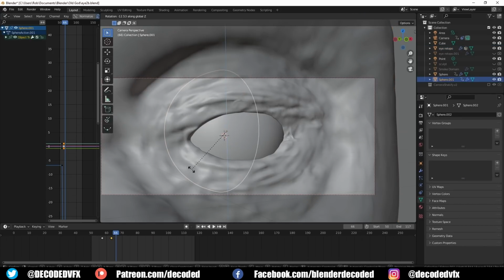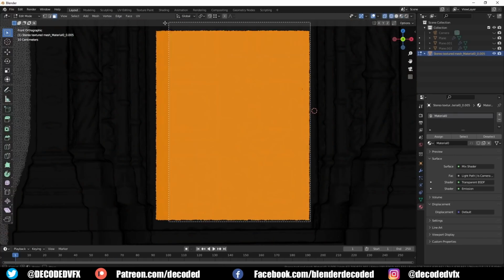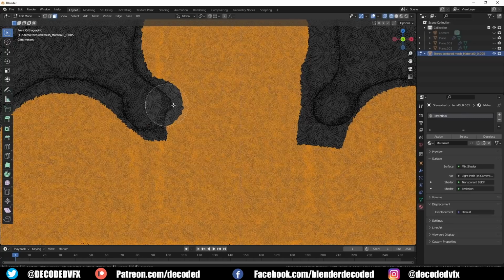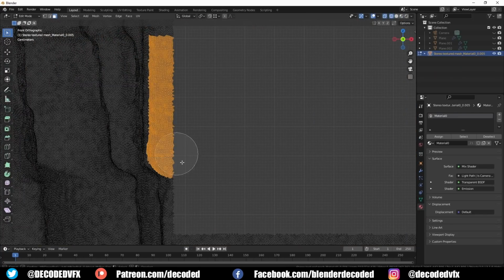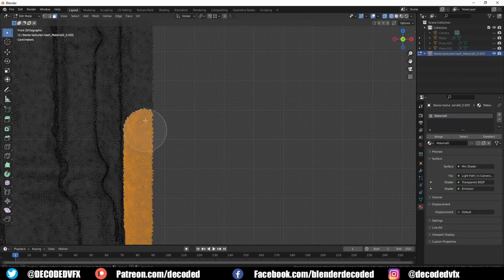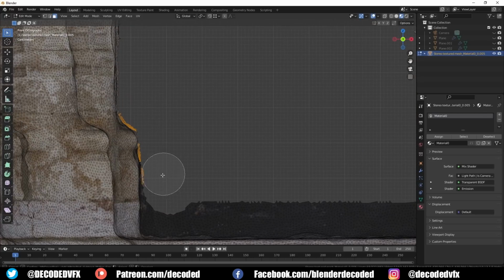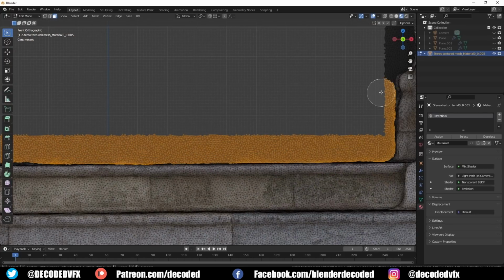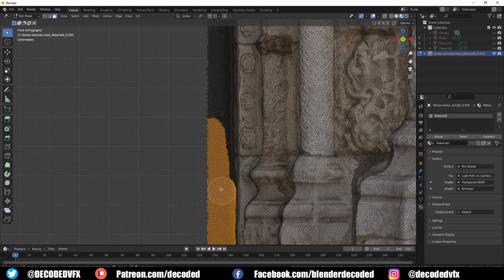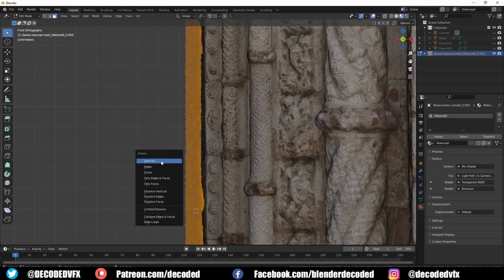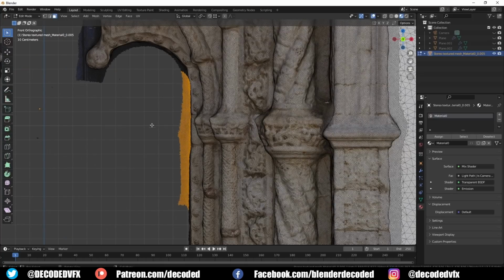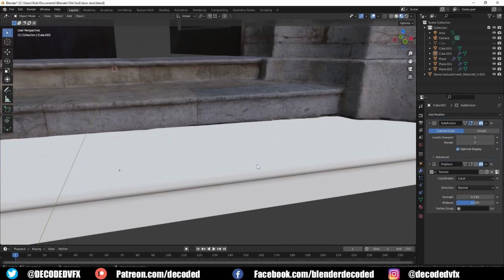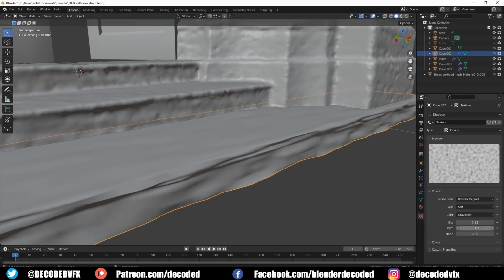To make that shot of the door opening, I used another 3D scan of a nice doorway, and I just deleted the actual door parts and I replicated them with some pretty basic geometry. Then I just moved those into the right position. One of the reasons that I picked this scan in the first place was because it has these nice mouldings that actually cover the door frame with a little bit of a gap. That made it really easy for me to kind of roughly select the parts of the door I needed to delete, and I knew it would hide the transition between what's the 3D scan and what's the geometry that I've made. I also managed to make some really simple steps for the door. I thought these were a pretty good match for the scan in the final render.